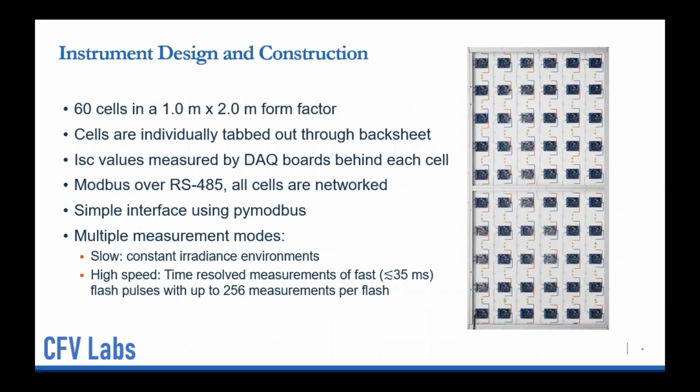The really cool thing here is that all of these are connected via an RS-485 network. So we actually have one power connection, one data connection in and out. So that's basically all we have. Other incarnations, as I've seen, have a lot of wires come off the back and make it kind of difficult to install in a variety of applications or installations. Additionally, it has a very simple interface, just using PyModbus. So everything here is basically Python analysis, including the data acquisition.